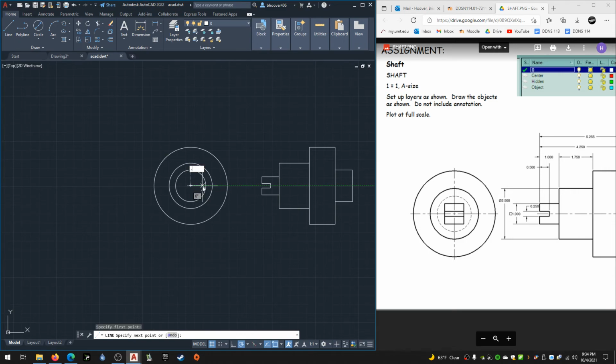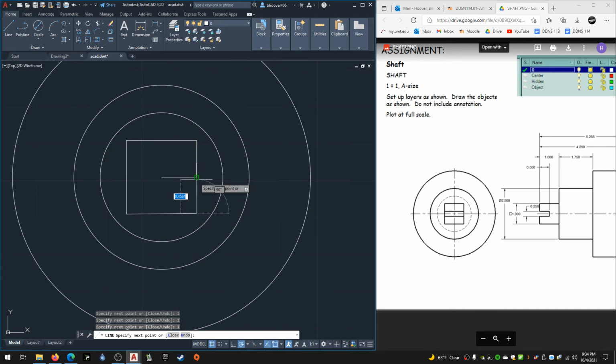You might be able to get that thing to work, but if not, you've got this center point, and then you can just go 0.5 both directions, 0.5, 1, 1, 1, and then back to here, stretch that across. I'll actually use this offset 0.125 both directions, and then I'll delete it like that.